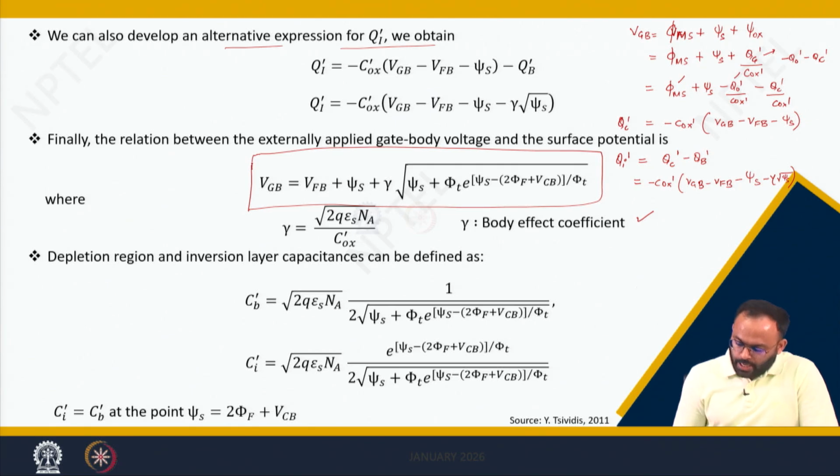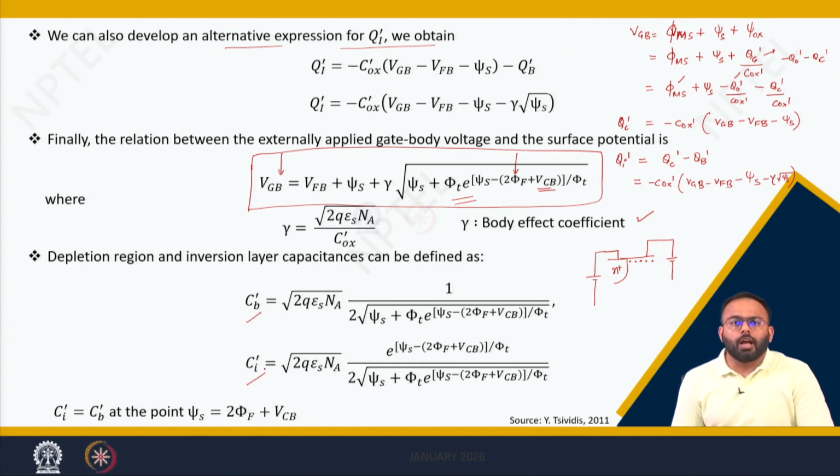Again, if you see here, the electron concentration at the surface is not only a function of Vgb. Instead, you can see that it is a function of Vcb also. So, the inversion charge present near the surface is not only controlled by Vgb now, it can be controlled by the external new terminal which is defined as C, and the Vcb voltage is actually controlling your inversion charge.